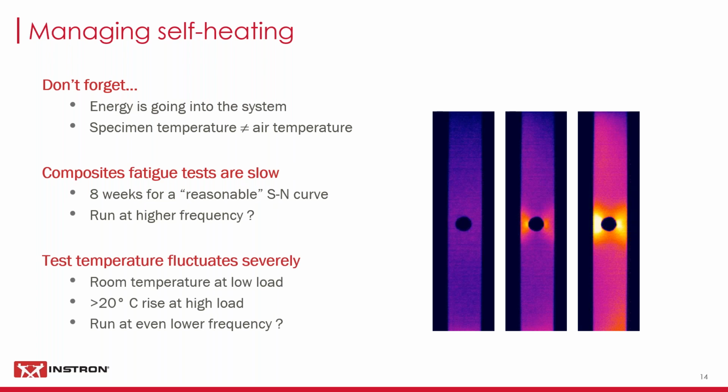The other aspect is that test temperature fluctuates severely. Highly loaded specimens will have a high temperature increase. Very lightly loaded specimens, actually, you don't really get much of a measurable increase in surface temperature.